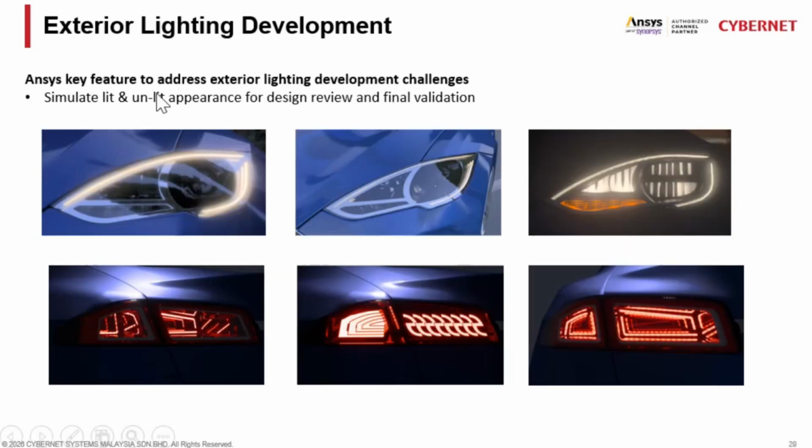The next one will be the exterior lighting development. Also, we can do the lit and unlit appearance simulation. We can light the light guide, and maybe lower down the intensity of the light guide, or we can simulate all the lights in lit condition during the night time. And also for the backline, the tail line, we can do it the same way.